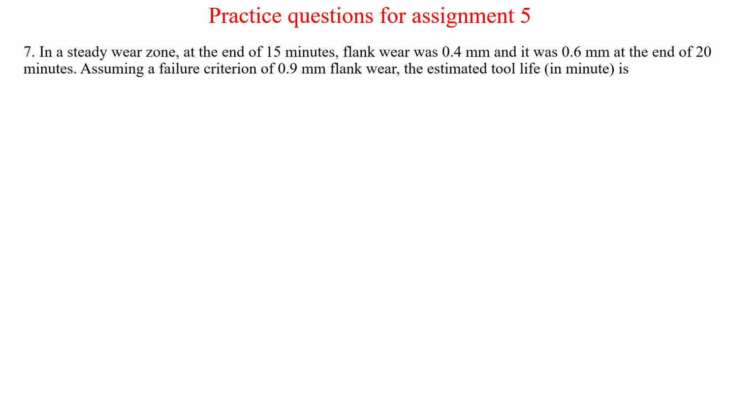Okay. 7th question. Please solve this question. In a steady wear zone, at the end of 15 minutes, flank wear was found to be 0.4 mm and it was 0.6 mm at the end of 20 minutes. Assuming a failure criterion of 0.9 mm flank wear, the estimated tool life is. Please try to solve yourself, then I will discuss with you. Please read the question very carefully.